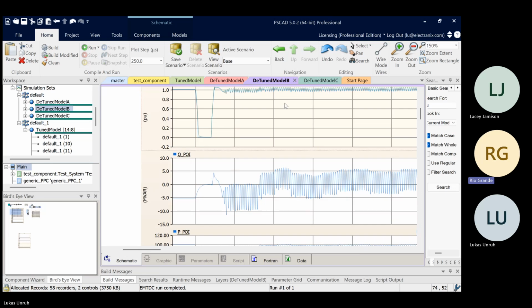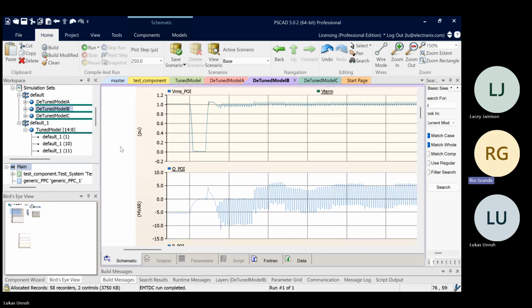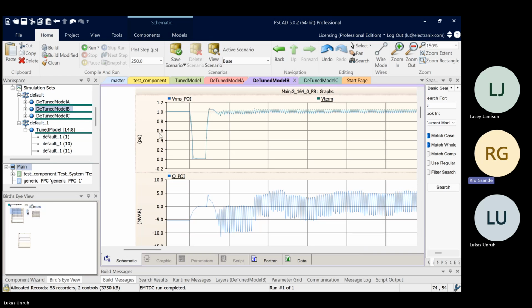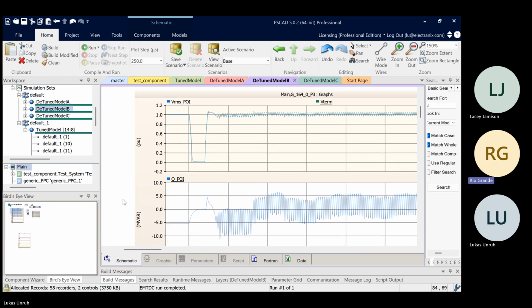So this is kind of just classical, well, this isn't actually the inner control loop. It's actually just before the inner control loop. It's just the active power regulator that sits just ahead of the inner control loops. But you could make this sort of thing happen by playing with any set of those gains.